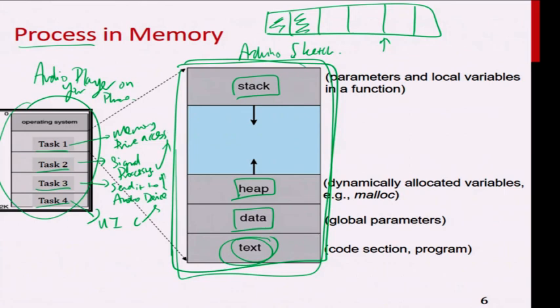So the most important thing: most students, when they learn about RTOS, think that the coding part is difficult. No, the coding part is not difficult. The design of your code is the most difficult thing. Because if the design in your head is all messed up, then whatever code you write, no matter how wonderful, you will still not be able to achieve the objective. If your original design of how many threads do I need, how do I pass the information around, how do I synchronize the information, is wrong, then no amount of coding will save you. So the most challenging part in a real-time systems project is the design. How do I design the system to fulfill the objective using multiple threads?